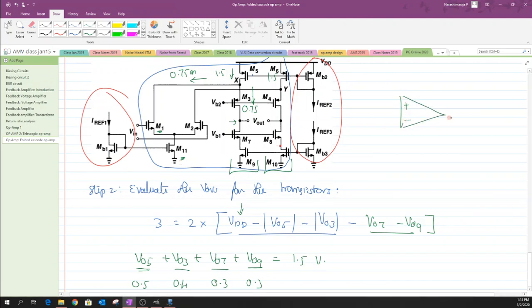Okay, let's assume that there is a unity gain feedback, and let us have our input here, and this is what we have. Now this connection can happen in this structure by shorting this output towards the input, right? So this short is actually making this output get connected to one of the input terminals of our op-amp. Okay, and that is basically created by this. Now right now, we are left with the common mode voltage that we have across this, and that common mode voltage is being applied as VGS plus VDS of M11. Okay, so hope that it makes sense.